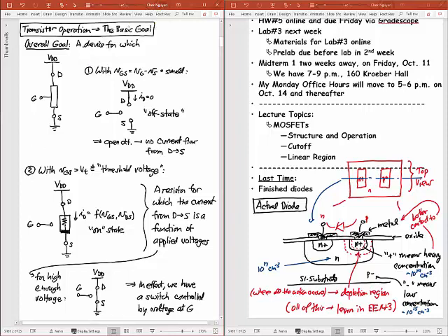Okay, it is thin. So I have this voltage VGS that I have here. That's actually my control voltage, right? I can't just say voltage at a terminal. Voltage is always between two terminals, right? And so if this is ground, then I have a voltage VGS. VGS, which is the voltage at G minus the voltage at S, if that's small, then I shut this off.